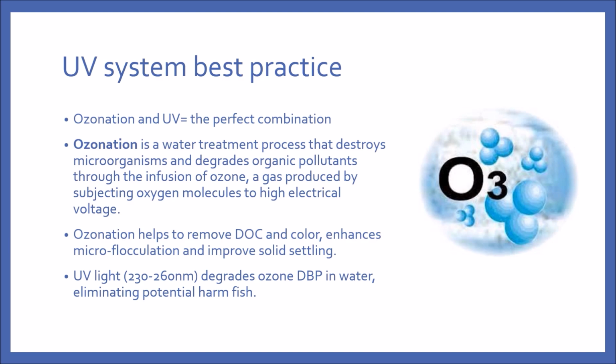In our plant, we are only utilizing a UV light, and the UV light we are using is about 90 watts. We have to proactively replace the UV light every 8 months. In some water treatment processes, it is common to include additional filtration steps such as microfiltration or ultrafiltration prior to the UV plant. In our case, we are utilizing what we call a protein skimmer to remove any fine solids before it is introduced into the UV system to ensure that our UV is at its peak performance.